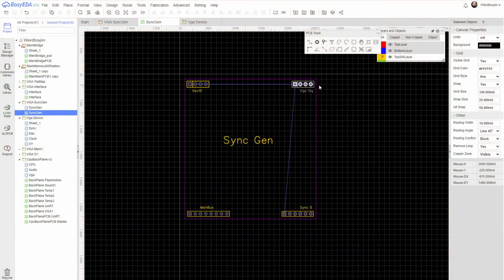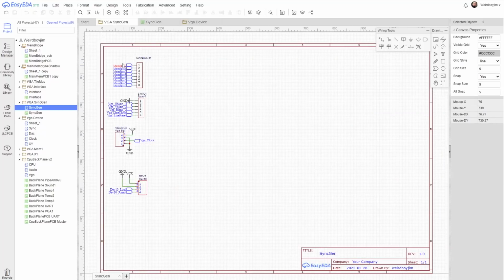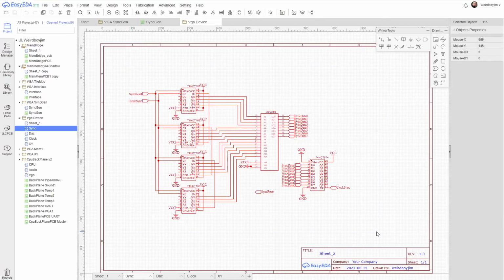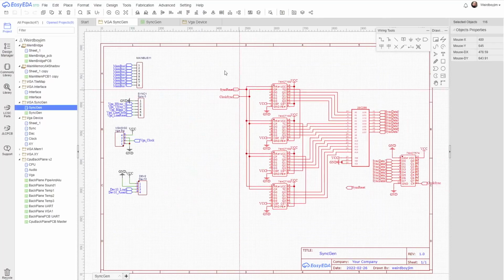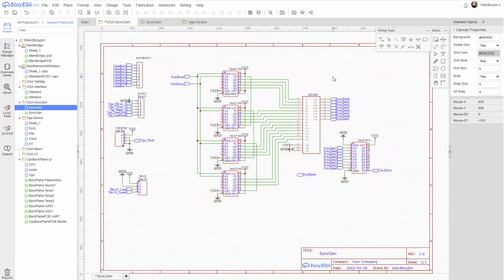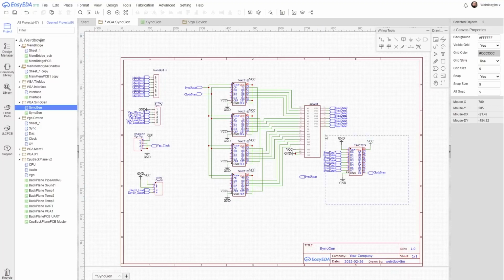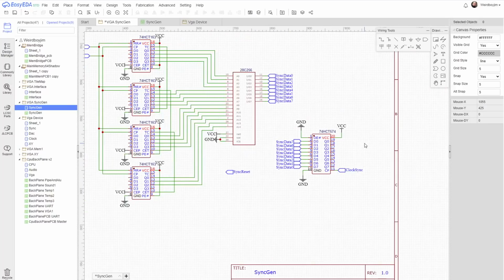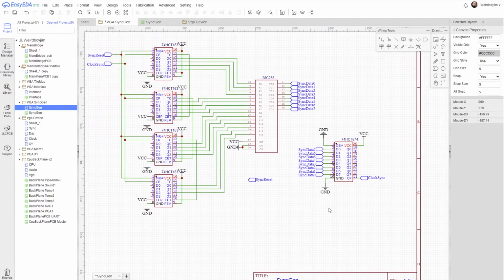Okay, so I've taken the footprint that we put onto the temporary backplane, lifted that out as its own little PCB as a starting point. So I've also got the connectors. But when we designed the VGA circuit, I did do this bit of schematic, so we can pull that straight in. Now this isn't quite everything, but it's quite a bit of it. Okay, so this 574 is gating the output.